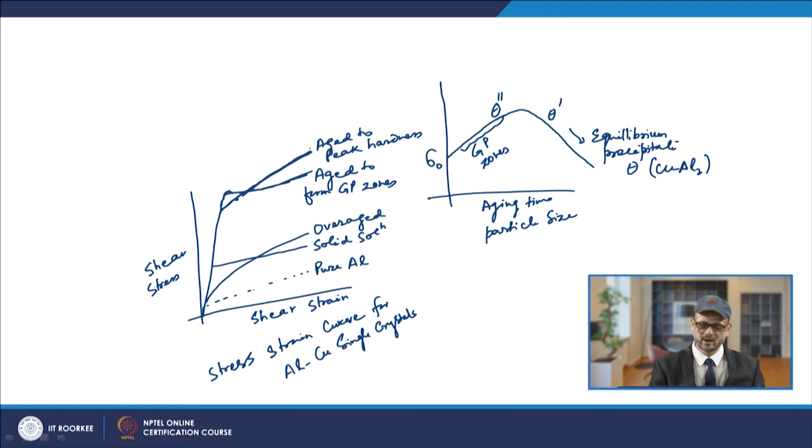And in this case, slip lines were found to be very short and distinct. So this suggests that dislocations are no longer cutting through. This is indicative of the situation where dislocations tend to bypass and have a bend type of movement in such cases. So that is what the situation looks like in that case.